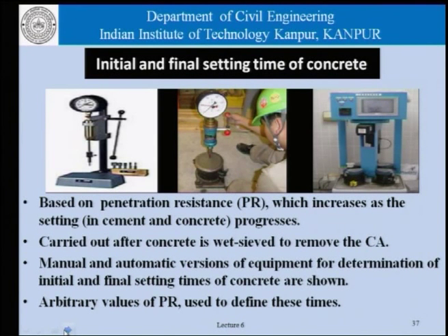This shows the actual setup. This of course is the same picture as we saw just now. This is the test for the setting times being actually carried out. We can see that there is a mold which has been filled with mortar. The concrete is wet sieved to remove the coarse aggregate, and what is left here is mortar. Here is the Proctor apparatus where we plunge a needle into the concrete and observe the penetration resistance on the dial gauge.